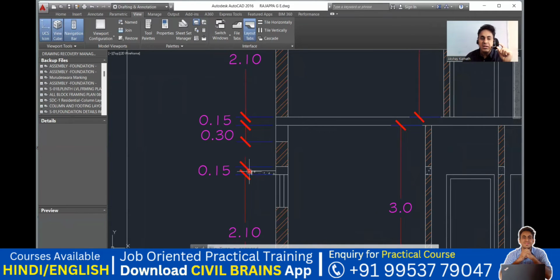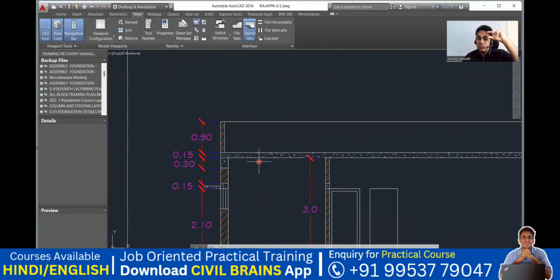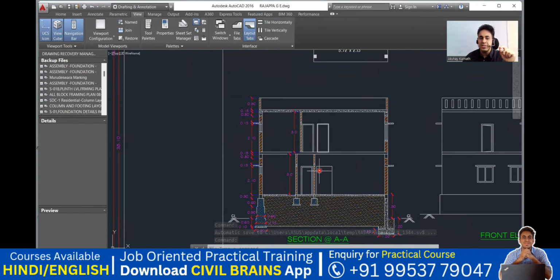Then the depth of the brickwork you're supposed to do is 0.30 meter. And then again, this is my first floor. In the first floor, from this floor level to the bottom of my lintel is again 2.10 meter. Then this remains the same. And what is the height of your parapet? It is mentioned here: the height of your parapet is 0.90 meter. Got it? So these are the door and the other parts.